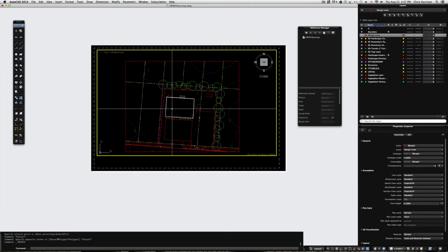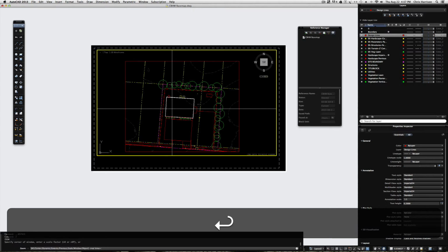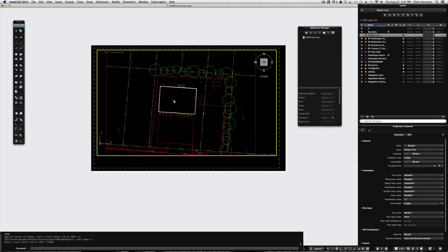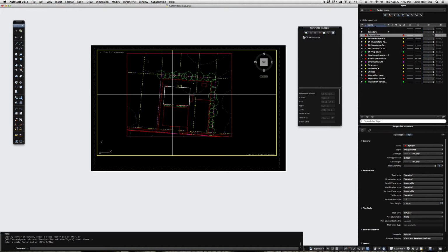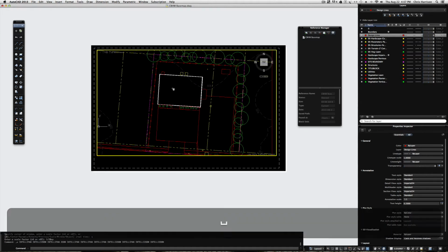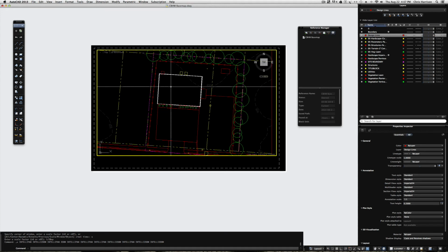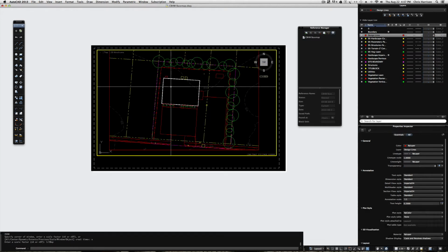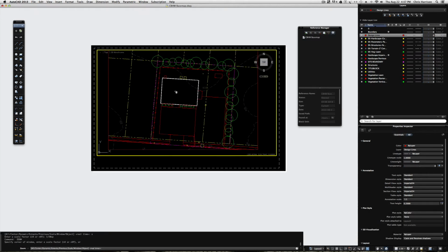Make sure you're there and typing Z, enter, S, enter, 1/20 XP, enter, and I'm going to hold the mouse middle click button so I don't lose my scale, because what you could do is shift out and you've lost your scale, so you don't want to do that. So let me Control Z that back. So there's my scale. That's the 20 scale that I want. Maybe not. 1/20 XP. There it is. Okay, there's the scale. That's what I want in my drawing, so cool.